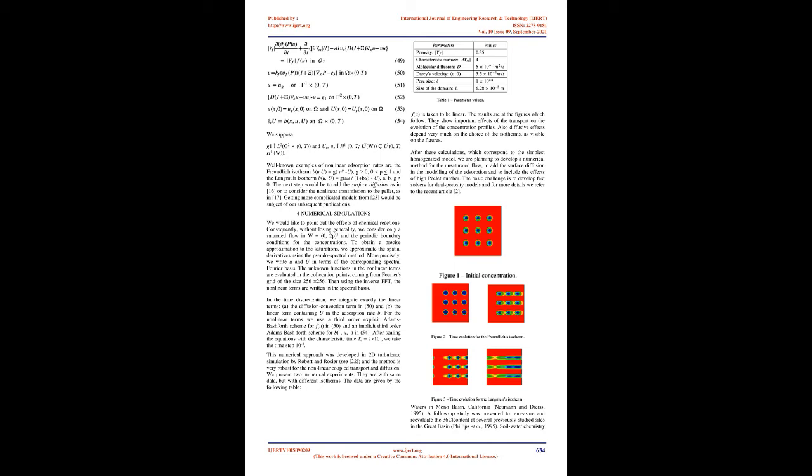Natural variations of stable isotopes were used to study infiltration in clay soils and groundwater recharge in the small drainage basin of Barogo in West Africa, Mathieu and Bariac, 1996. The isotope analyses led to the characterization of 2 separate infiltration processes as well as 2 recharge processes.